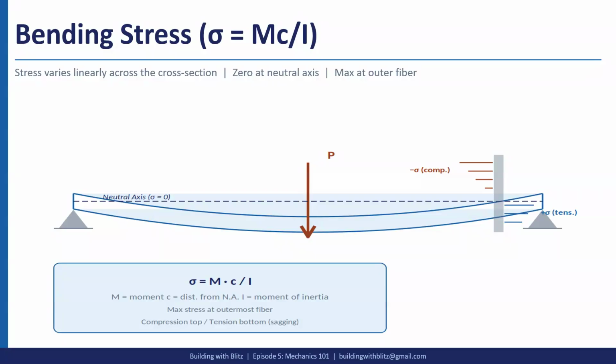Or if you're looking at a composite member, for example, if you have a change in material at 3 inches from the neutral axis, but your total member depth is 6 inches or 8 inches per se, you can take a look at any length along the neutral axis. Just know that if you're 2 inches away from the neutral axis, and you're looking at compressive stress, you're going to have the same value 2 inches on the other side for constant cross-sectional geometry of a tensile stress. So you have equal parts.